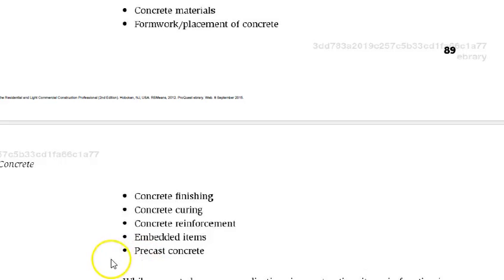The thing about precast concrete and why it's more and more popular, especially when you think of things like Rapid Construct, is that in a factory you can control the conditions much better. You can ensure mixes are to the exact quality that you want. You can cure the concrete in controlled conditions. So more and more we use precast concrete. It's a good choice if you can, but still, again, if you have good working conditions outside, you can do a lot with your concrete.